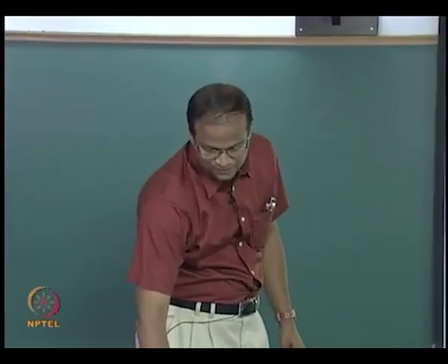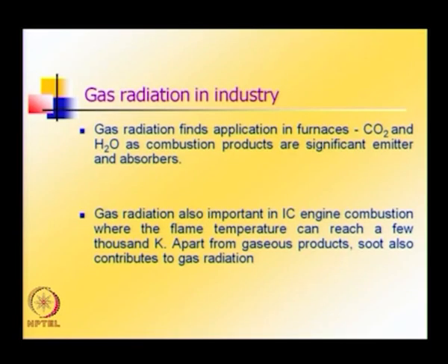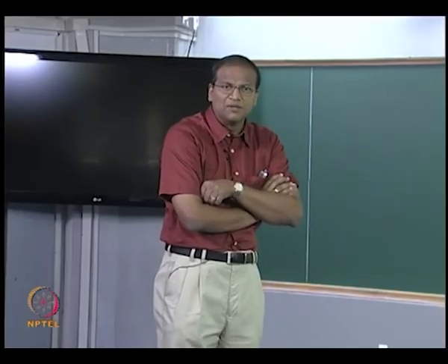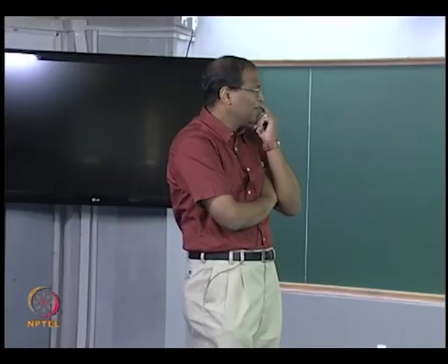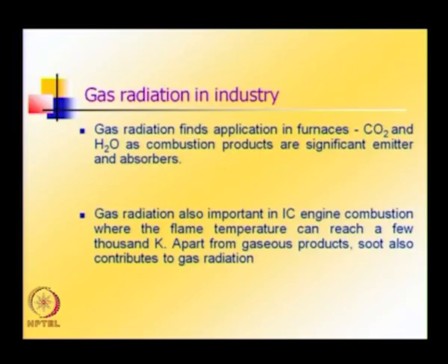There is one journal. Okay, what about gas radiation in industry? Gas radiation finds application in furnaces. Carbon dioxide and water vapor are combustion products. They are significant emitters and absorbers. These gases are found in furnaces, combustion chambers, and IC engines. Gas radiation is also important in IC engines, where the flame temperature can reach a few thousand Kelvin.